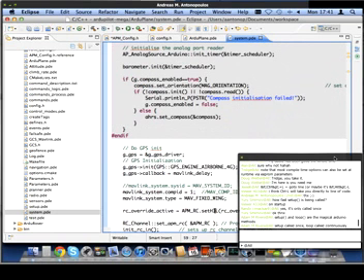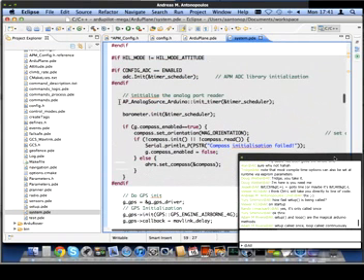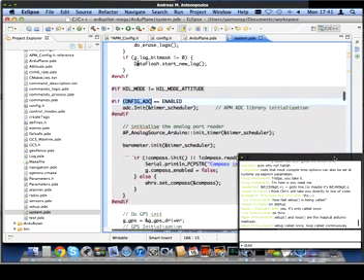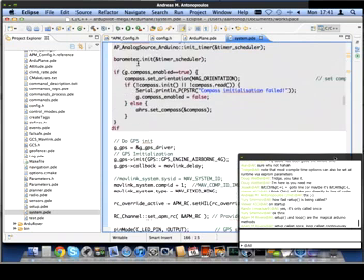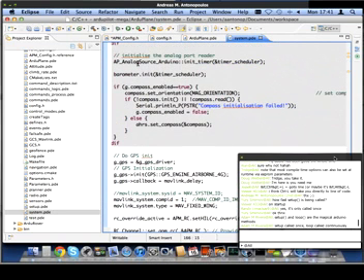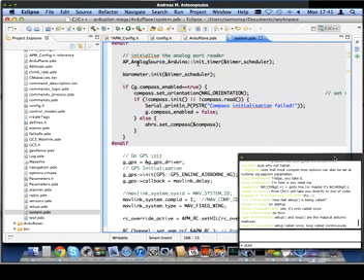On the APM2, things are different. It doesn't have that ADC chip, and so that's why there's an if-def, as Andreas explained earlier. Those if-defs come out of config.h, and when you enable APM2 hardware, one of the biggest changes is that we don't use that ADC chip because it doesn't exist on the APM2. Instead, we have a different way of reading on the SPI bus to get the digital readouts from the MPU 6000 gyroscope, accelerometer, etc.